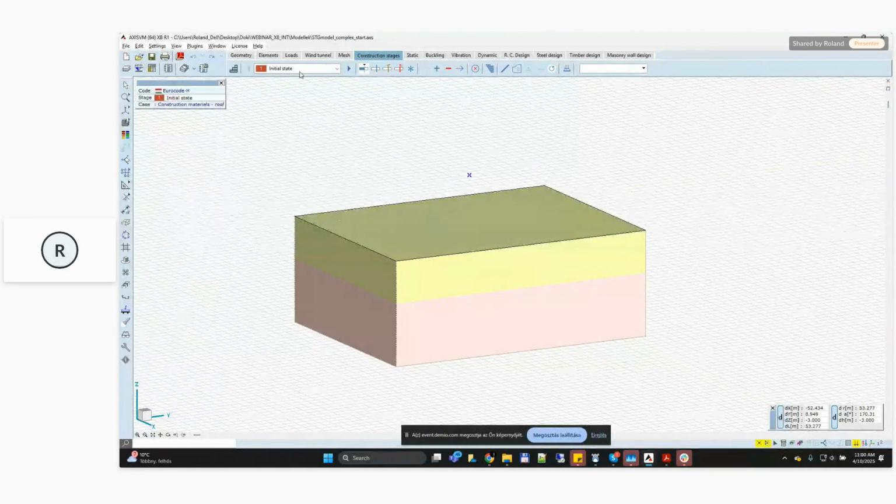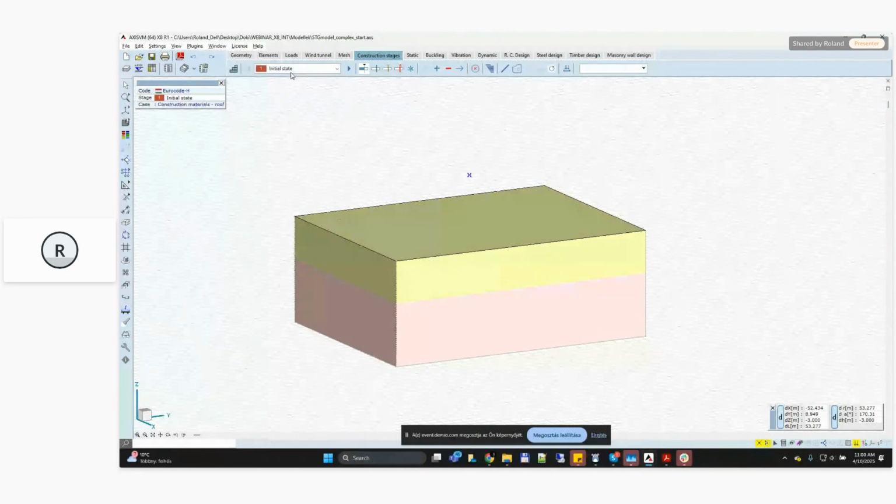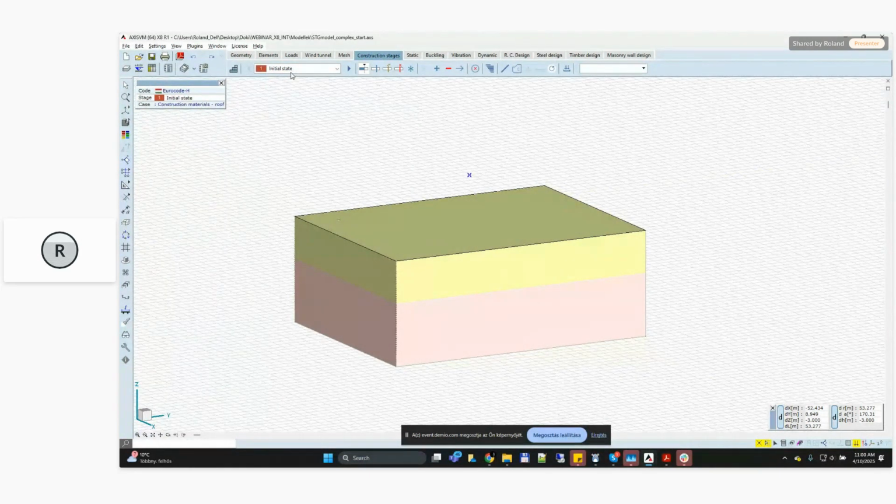And this is modeled because we want to take into account the initial state of the soil, and the deformation differences between the supports. We do not want to define stiffnesses for each of the supports separately, but we want to assess the stiffnesses based on the soil deformation itself.